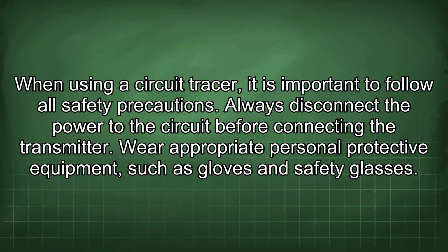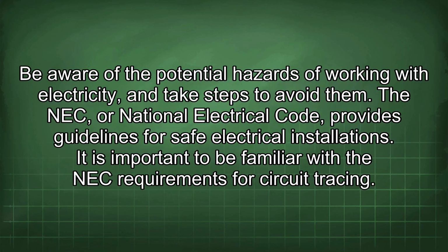When using a circuit tracer, it is important to follow all safety precautions. Always disconnect the power to the circuit before connecting the transmitter. Wear appropriate personal protective equipment, such as gloves and safety glasses. Be aware of the potential hazards of working with electricity and take steps to avoid them. The NEC, or National Electrical Code, provides guidelines for safe electrical installations.